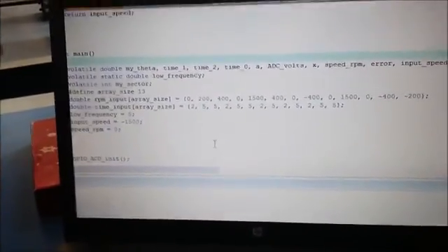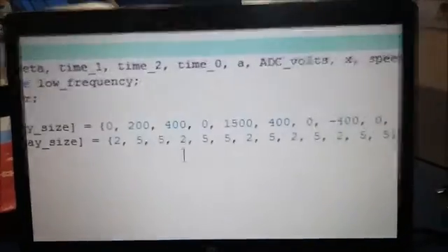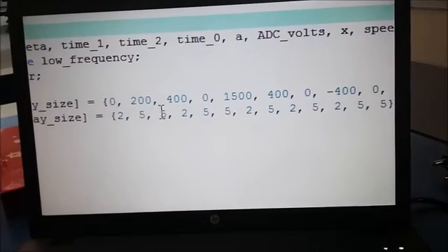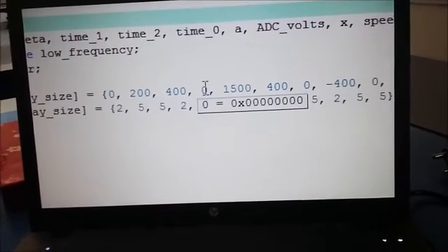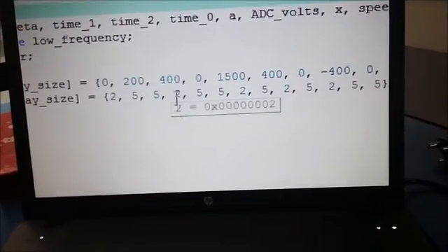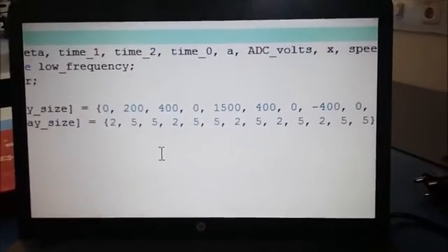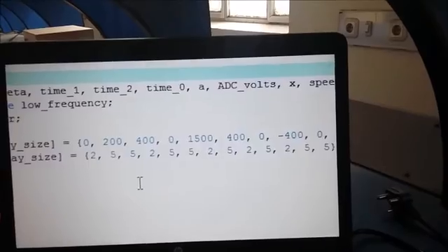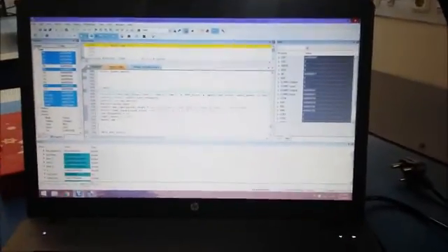So our motor will run at 200 rpm for 5 seconds. Then it will run at 400 rpm for 5 seconds. Then it will stop for 2 seconds, and so on. So this is a trend, or we can say that our AC drive of induction motor is programmed, and it will iterate this trend and continue to rotate in this situation.